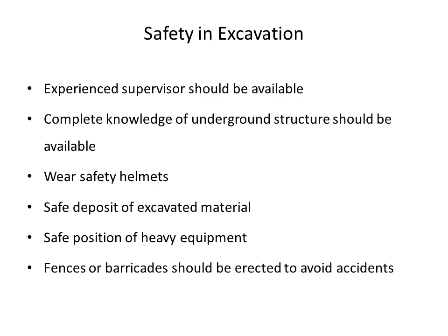Then positioning of the heavy equipment. Heavy equipment such as dragline, JCBs, etc. should be placed away from the excavated site. Otherwise, the ground is already disturbed, and if the heavy equipment is placed near the trench, there is a chance of sliding of the soil in the nearby areas. So that should be avoided.